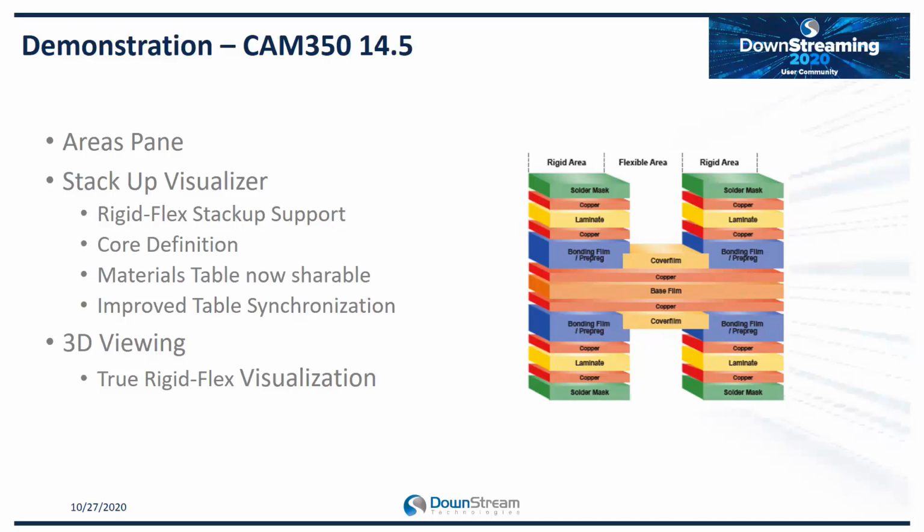Now, I know there's a Rev C coming out from the IPC consortium, and there's more proper support for rigid flex in that platform, and we will support it. Today, Cadence is writing what we call IPC 2581 B plus. So they are writing sort of a B formatted file with C data in it. And we do accept that because we're testing to it. So we'll probably be, if you will, C ready by the end of the year. But of course, should the consortium make a change between now and its spec release, we'll have to catch up.